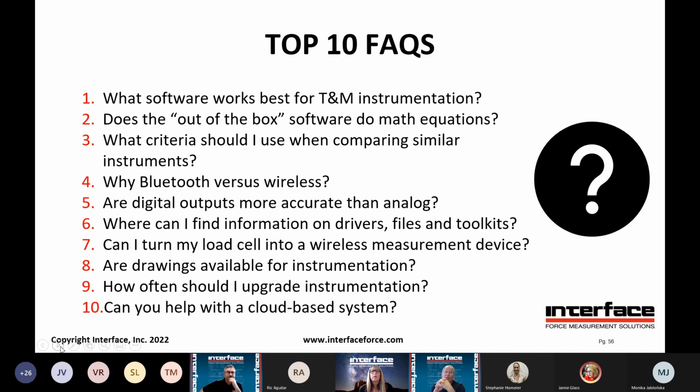What are some of the criteria I should use when I'm comparing similar instruments? Well, as Ken mentioned with the selection guide, you really have to understand what you're trying to do: how many channels, what existing hardware you're trying to interface with, what sensors. A lot of times, you're talking to us about load cells, but what other sensors do you have? A lot of these boxes have extra input channels, so you can actually add sensors that you may already have. So it's good to look at the whole system and make a decision that way, instead of looking at it piece by piece.